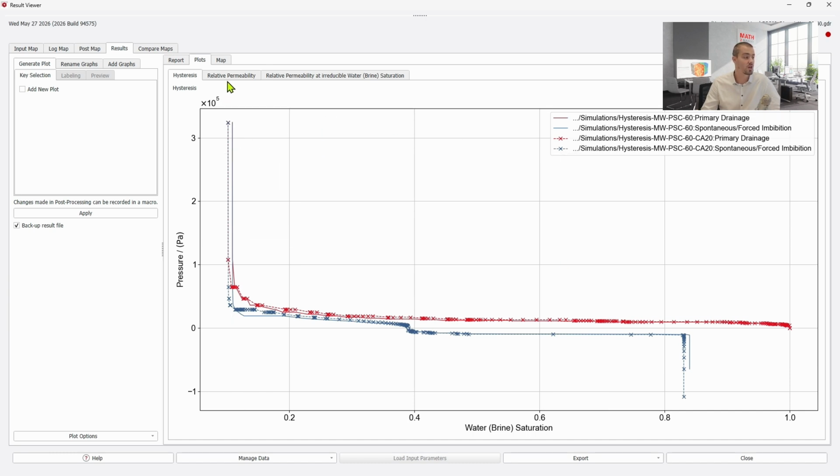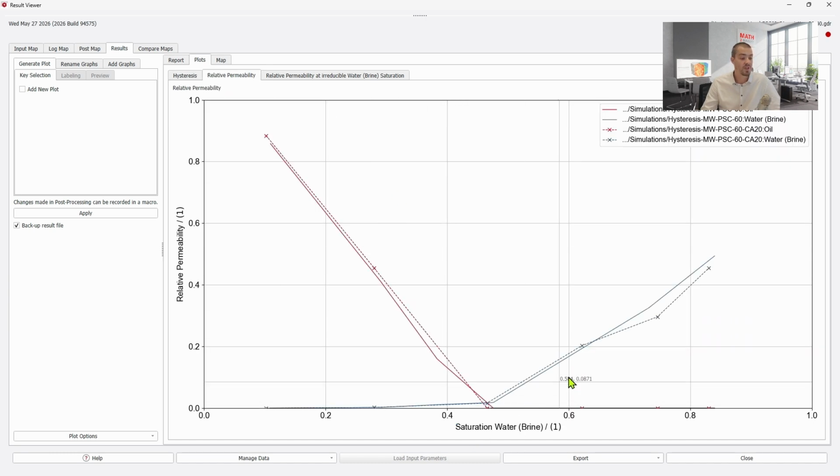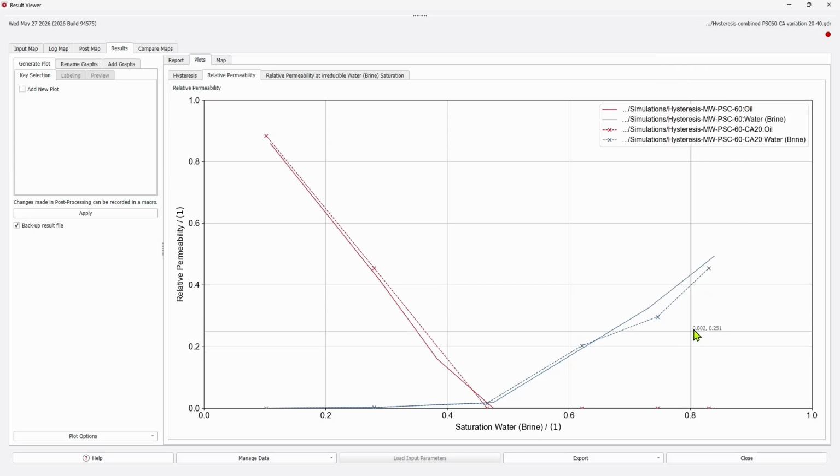of the capillary pressure curve. Now also looking into the relative permeability behavior, we can see that the case with the more, so to say, water wet conditions, which is the contact angle 20 and 160 after aging, we have higher oil and lower brine mobility, which again goes quite well in line with experimental observations.